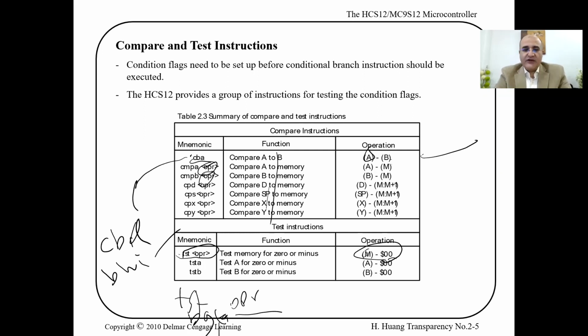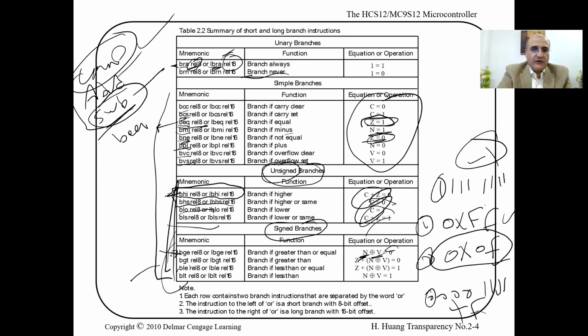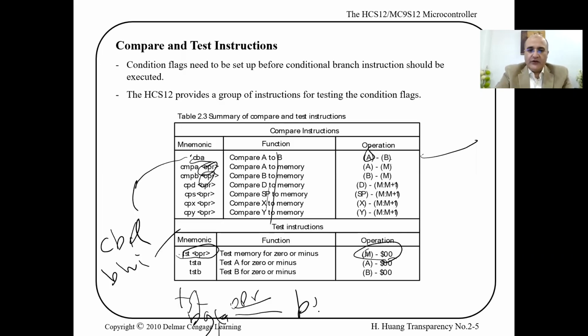If you want to check if the operand is 0, you use branch if equal or greater or equal, or if you want equal alone, branch if equal, BEQ. It will check for the Z flag alone. So it will subtract 0 from a number. If you subtract 0 minus 0, the result is 0, the flag will be raised, otherwise it won't.